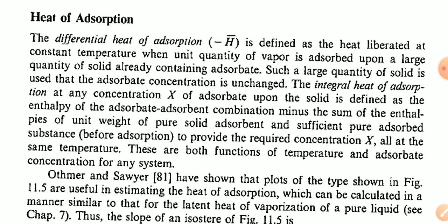The integral heat of adsorption at any concentration X of adsorbate upon this solid is defined as the enthalpy of the adsorbate-solid combination minus the sum of the enthalpies of unit weight of pure solid adsorbent and sufficient pure adsorbate substance before adsorption to provide the required concentration X, all at the same temperature.